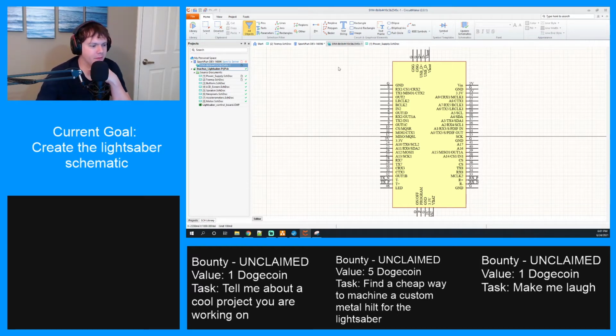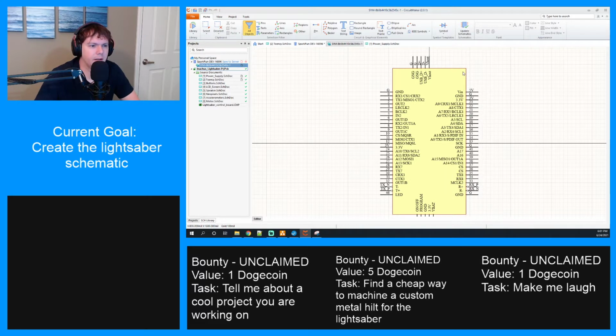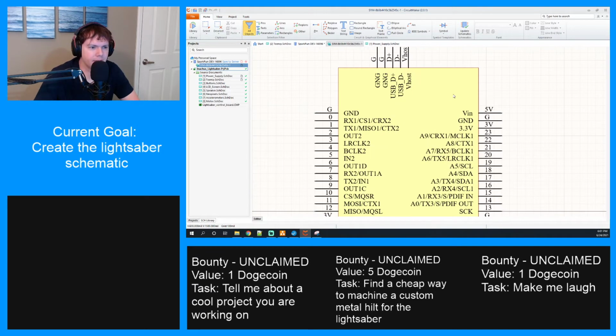So what we're going to do here is add 2 more pins, which are for the USB port that you program the Teensy with. There's a couple pads underneath it that you can hit with pogo pins or something. And I want to add those here because I'm going to have to do that in my circuit. So let's do that.